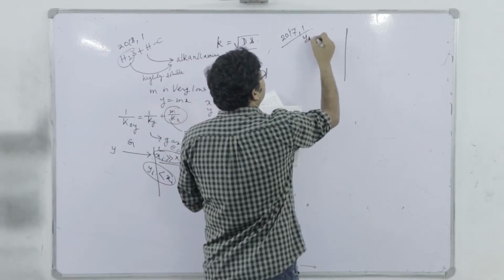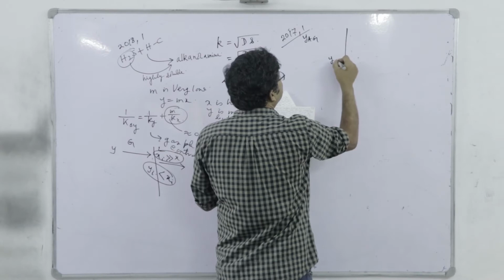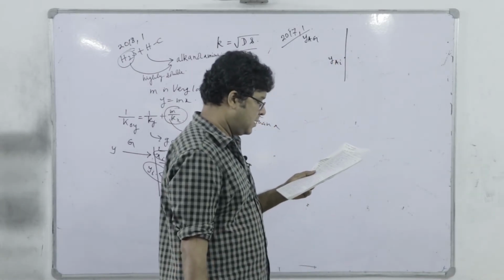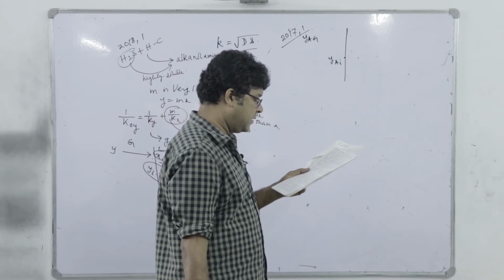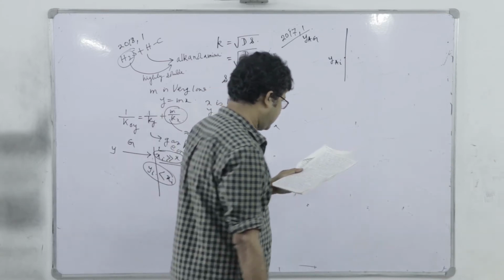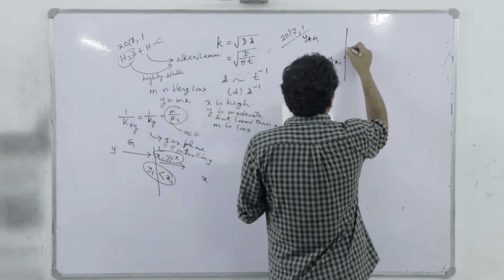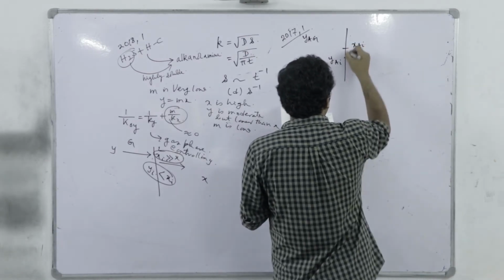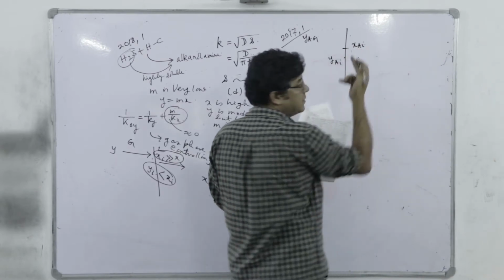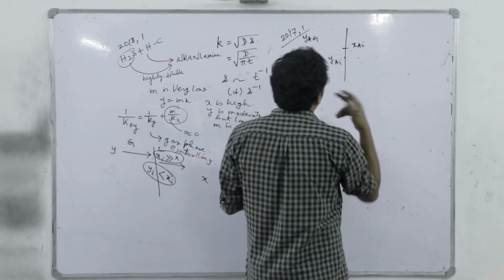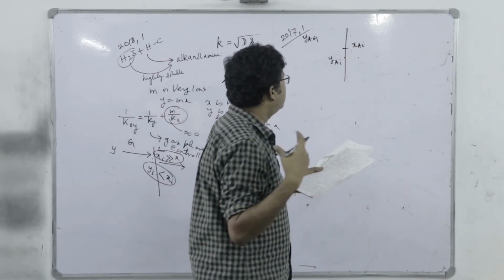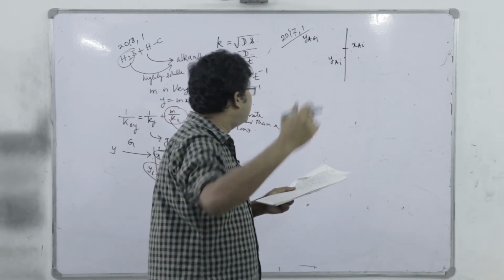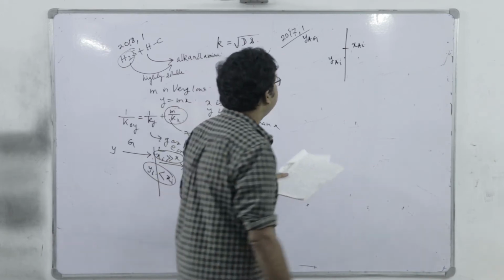So here it is YAG, here it is YAI. Right. The liquid phase bulk and interphase mole fractions are XAL and XAI. So let's have here XAI. It may be above or below, that depends on what is the value of m, right. So if m is low, which means the gas is highly soluble, XAI should be above and over YAI.